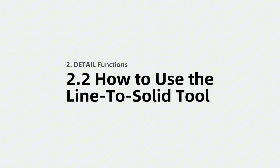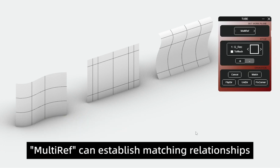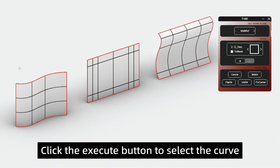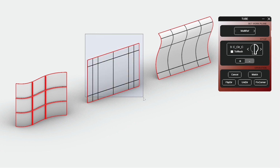How to use the Line to Solid tool. Click Tube to open the Line to Solid tool. Multiref can establish matching relationships between multiple curved surfaces and curves. Switch the section type. Click the Execute button to select the curve, and press the Enter key to generate a solid object. Switch the section type, and generate solid objects again.